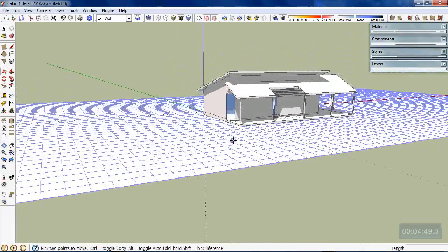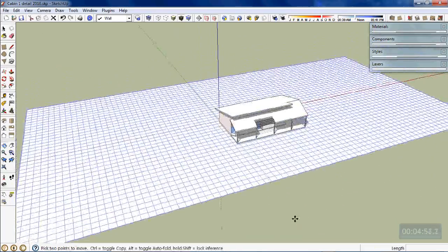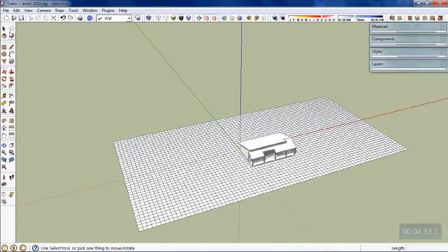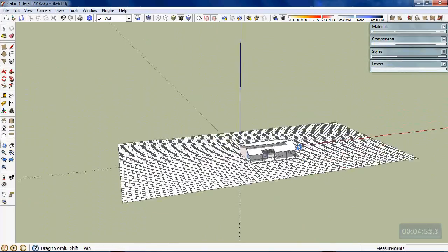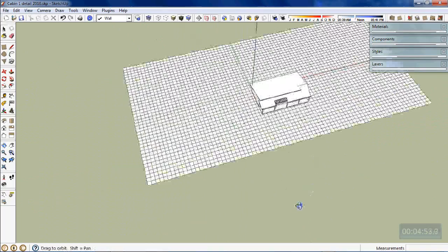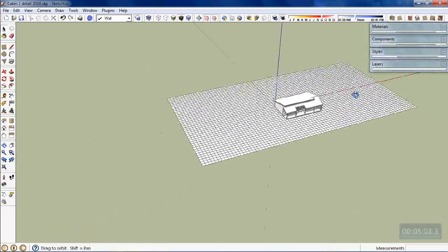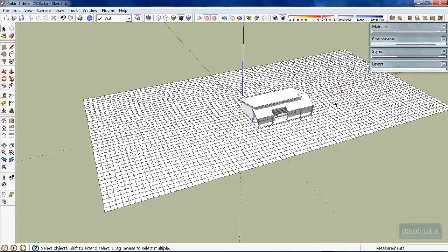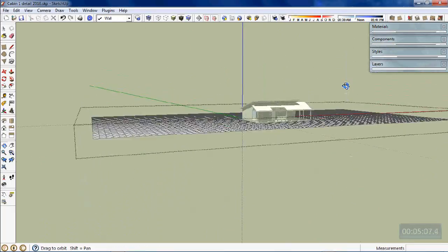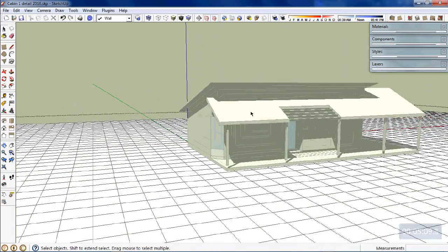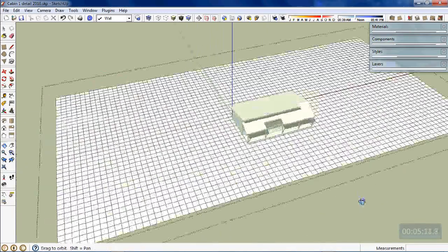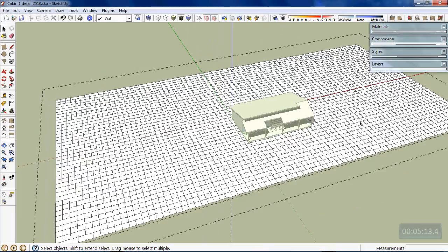Now, after you've established that, the grid has been turned into a component. There's a whole lot of individual lines and faces that have been turned into a component. Now, what you need to do to edit a component is double click on it. So I've double clicked on that component, and as you can see, everything else has been greyed out, and just this component is now in heavy. I'll go back to my sandbox tools.